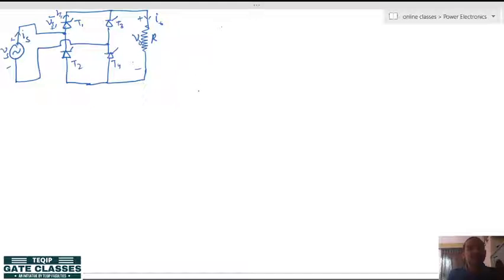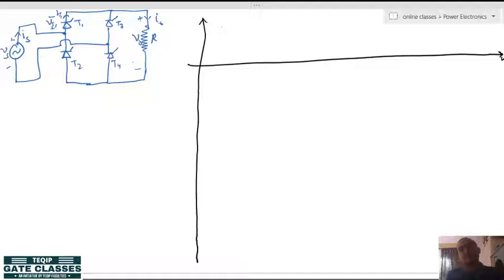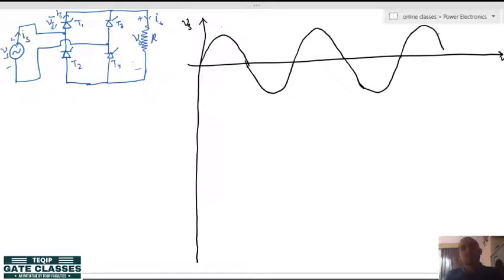The only difference is that in case of diode you have got instantaneous turn on and instantaneous turn off as soon as the diode is forward biased or reverse biased, but in case of thyristor it is not the case. The thyristor will not turn on unless you provide the gate pulse or the triggering pulse to the SCR. I have already explained this in my previous lecture also, that with the use of thyristors we can control the phase of any input sine wave. That is why they are also known as phase controlled rectifiers, because you can easily control the phase of the input sine wave, alright.